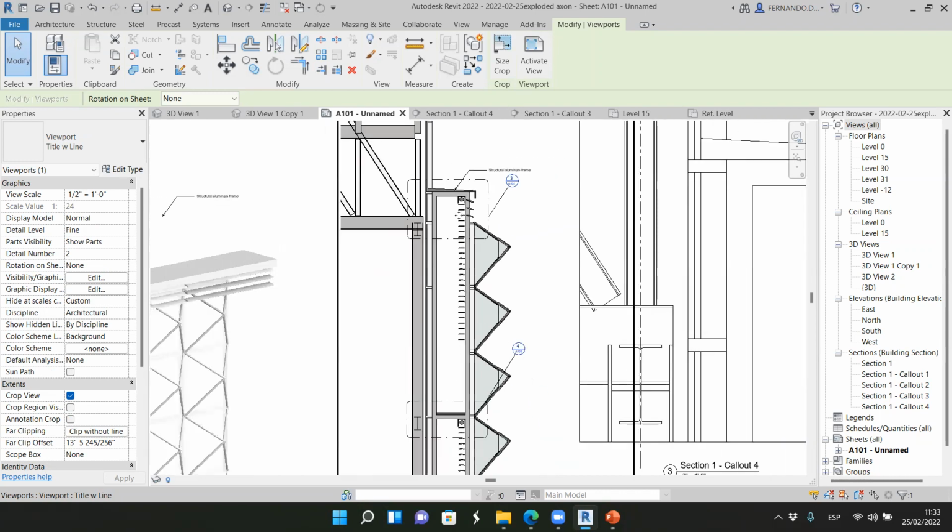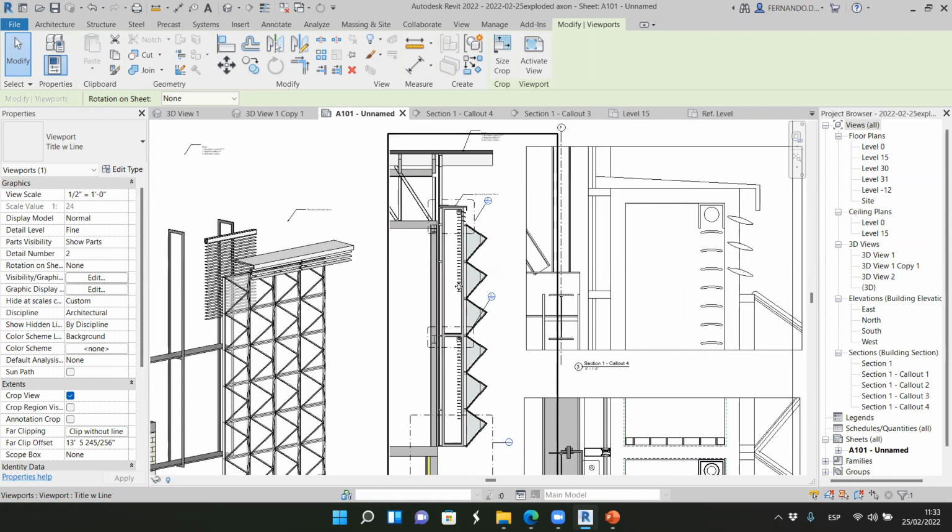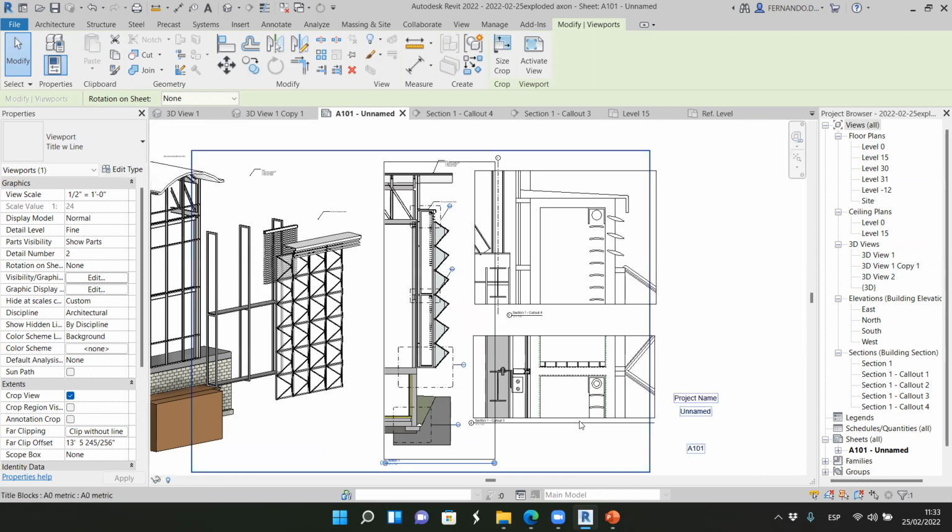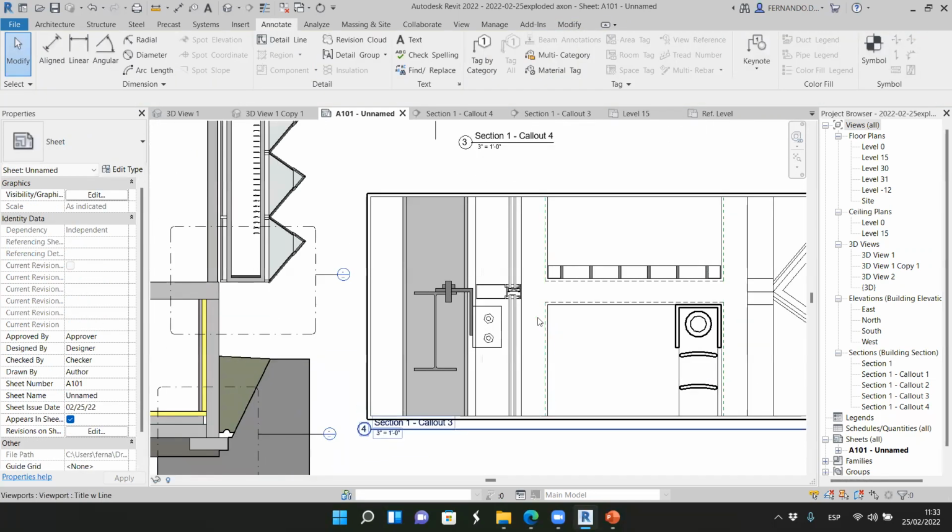And if those louvers can be moved, it's great because we can have sun in winter and we can have shade in summer. And then it's about connecting things. So we have the vertical and the horizontal structure. And then we have a curtain wall. So the curtain wall has to hang from the structure.